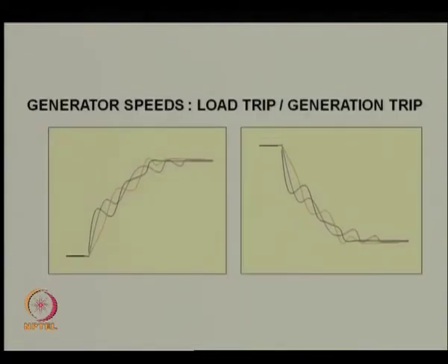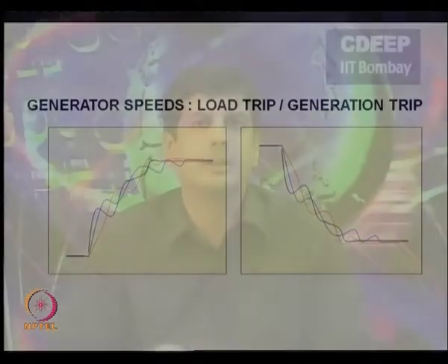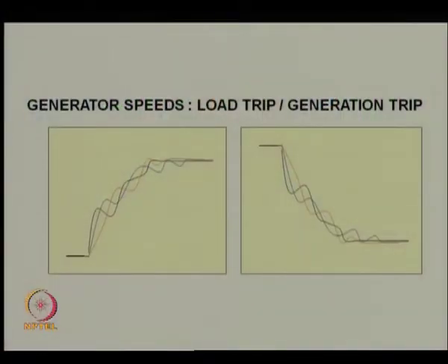What we should consider is, for example, a sudden load trip. If the load trips in a system, there will be a transient imbalance between the cumulative generation and the cumulative load. So, if there is an existing load and it gets tripped, there is an imbalance between the total generation and the total load, and as a result the center of inertia of the system accelerates. If you look at the first figure on your left, you will find that as soon as such a disturbance occurs, there is some relative motion and the system frequency tends to rise and settle to another frequency.